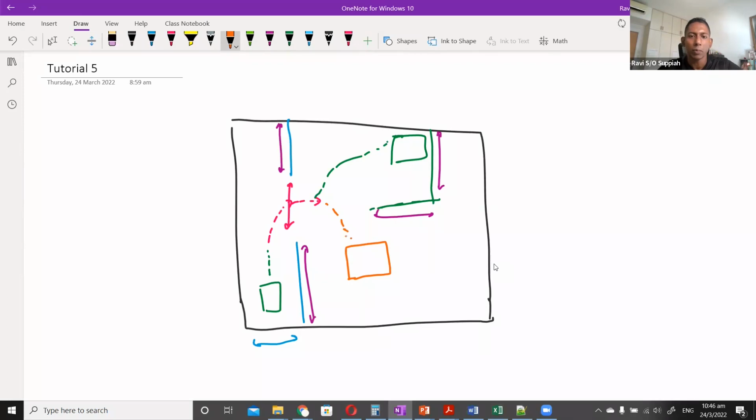Okay, and then you come to a point where you try to move but you cannot move. Why? Because you are hitting the hump. Whenever you can see that you're trying to move but the LiDAR map doesn't show any change, there's a high chance you're stuck at the hump. That is where you need to backtrack a bit and then move forward with a slightly higher speed, so you can get over the hump and move on. That is the only other thing you need to try out once we put up the hump.